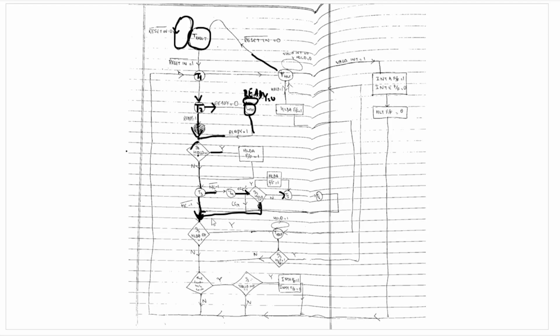So you can see that all those machine cycles only consist of T1, T2, T3. After that we need to go to the next machine cycle. Now if it is an opcode fetch machine cycle that has only T1, T2, T3, T4, it will rejoin that path. But if it has T5 and T6 additionally, as we have seen in some opcode fetch machine cycles, then T5 and T6 states will be entered, and then the microprocessor will follow this path.